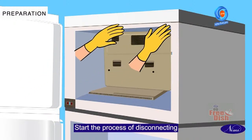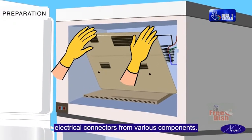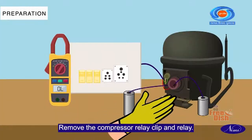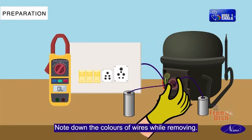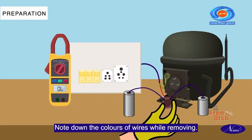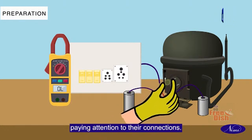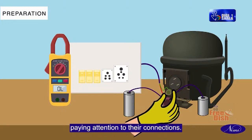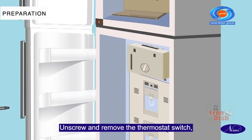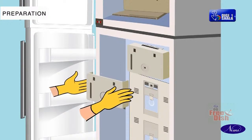Start the process of disconnecting electrical connectors from various components. Remove the compressor relay clip and relay. Note down the colors of wires while removing. Remove relay wire and junction wire, paying attention to their connections. Unscrew and remove the thermostat switch, noting its position and connections.